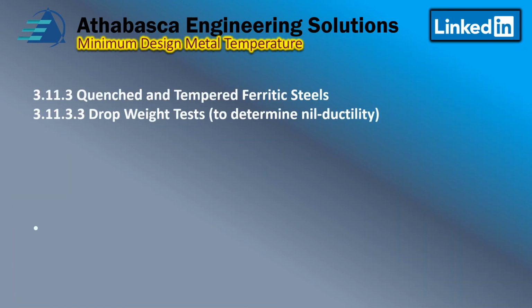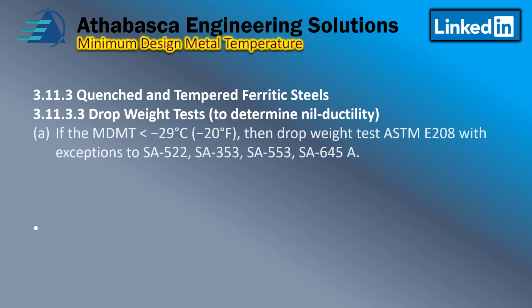Quenched and tempered steels allow for drop weight tests to determine the nil-ductility range. If your MDMT is less than minus 29, then you can use a drop weight test to avoid the impact testing. But there are exceptions, and the alloys are shown there.